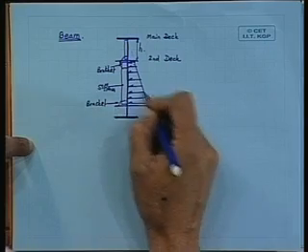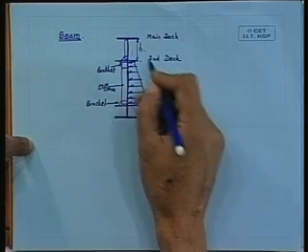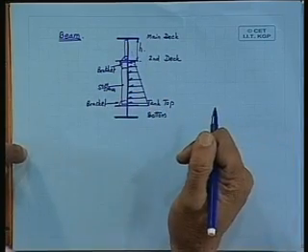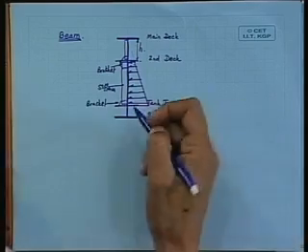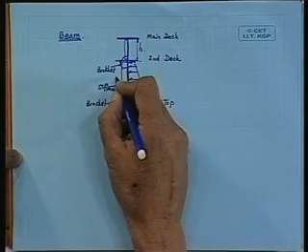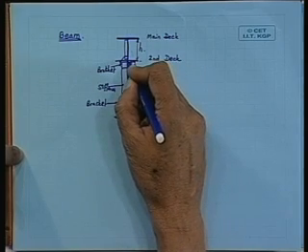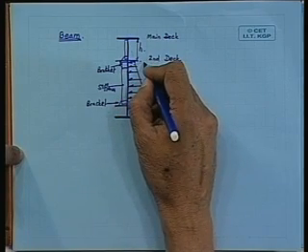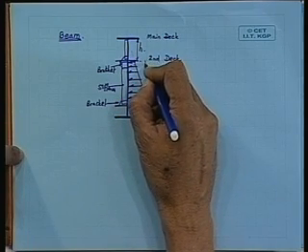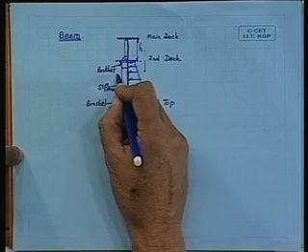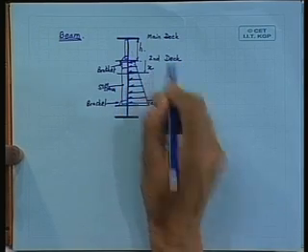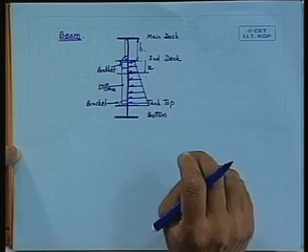Right? Now, here my primary member is between the second deck and the tank top, because the span is more and the load is of this nature. So, we are considering it as a beam. From here I set up some coordinate system and I say that my x is measured this way to some level here, right.